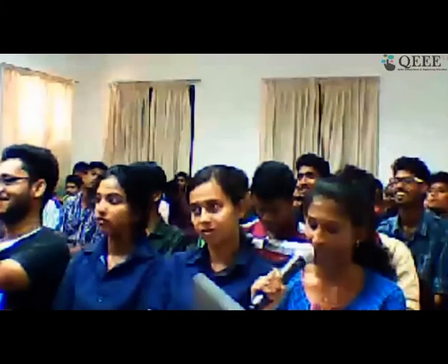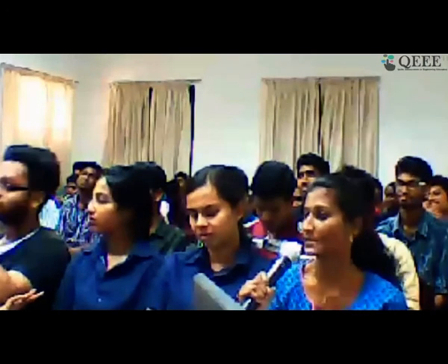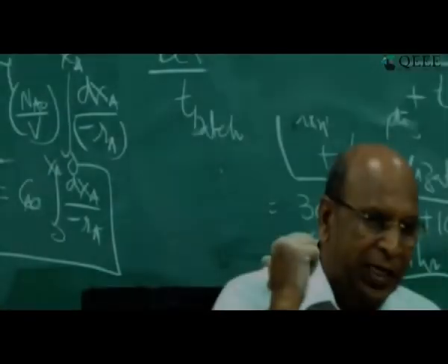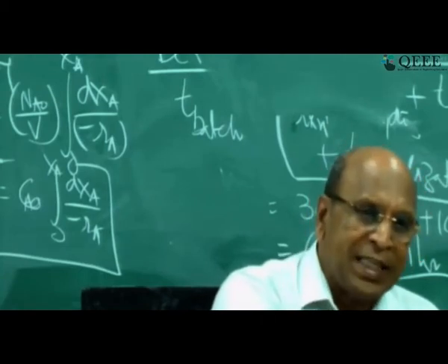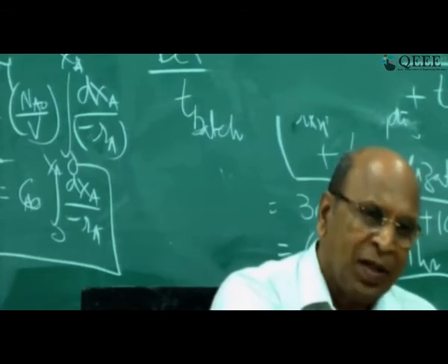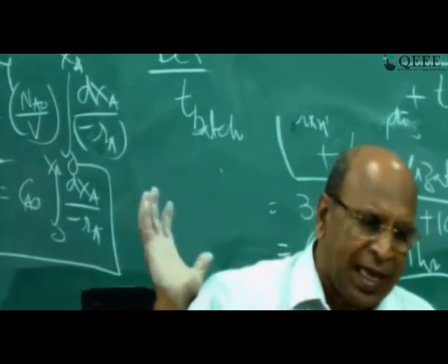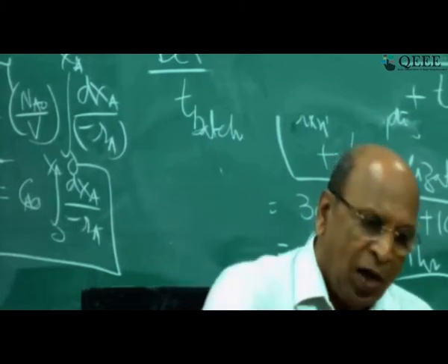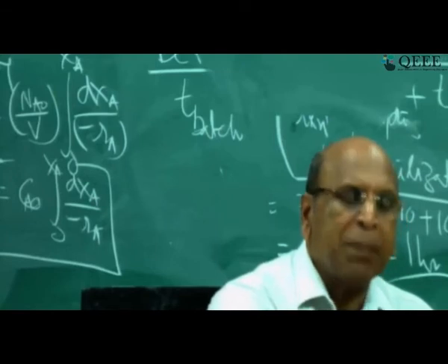Thank you. My question is, how can we ensure better mixing in tubes or tanks, especially when reactants in slurry form are used? Yeah, slurry. See, we are talking about homogeneous reactions right now, right? When you have slurries, it is no longer a homogeneous reaction. You have what is called a heterogeneous reaction, and that part I have not covered. For heterogeneous reactions, the procedure is the same, the same reactor design expression, right? And even for slurries, there are very good impellers that can provide good mixing.